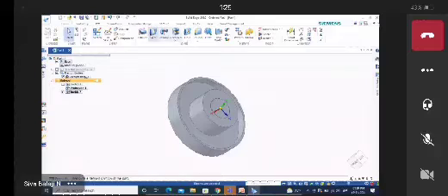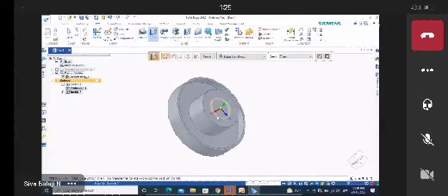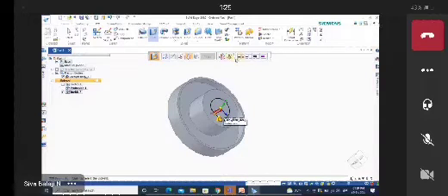Finish. Cancel. You can select the cut command here. Select the already developed sketch. You can accept that one and select cut from. Select the cut through all command and you can show the direction here. Okay. Cancel, and you can check it here.